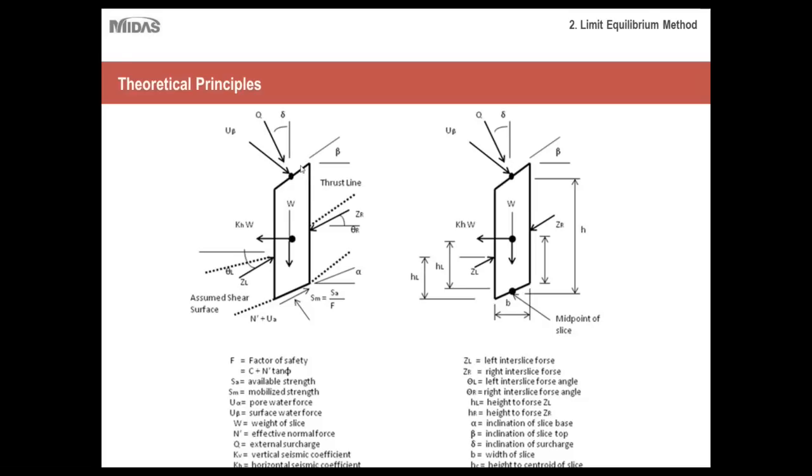As you can imagine, to do this by hand would have been a very long and iterative process, because you have to calculate these forces for each and every single slice, and then take those calculated forces and apply them to a factor of safety equation, which I'll show you momentarily. So hopefully this gives you a better appreciation of what these programs do for you, as they take a process that was very long and iterative and compute it automatically, so that you can focus more on the input and the results, as opposed to the actual calculations.